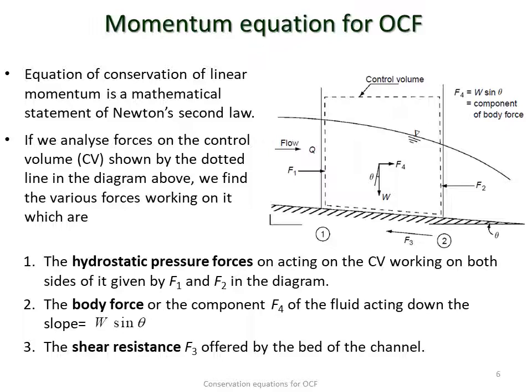And if the weight of the fluid in this control volume is given by capital W, then the component of the body force along the longitudinal direction is given by W sine theta. Theta is of course the slope, the inclination of the bottom of the channel, so it's the bottom slope. More or less these are the forces we will be taking into account while deriving the momentum equation.